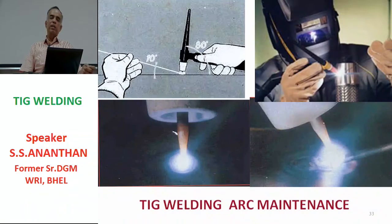Once the arc is initiated, the tendency for the welder will be to maintain the arc steadily. Now you can see in the picture, two photographs of the torches are shown. On the left side, the torch is kept vertical, and this is how the welder will start when welding is initiated as soon as the arc is established.